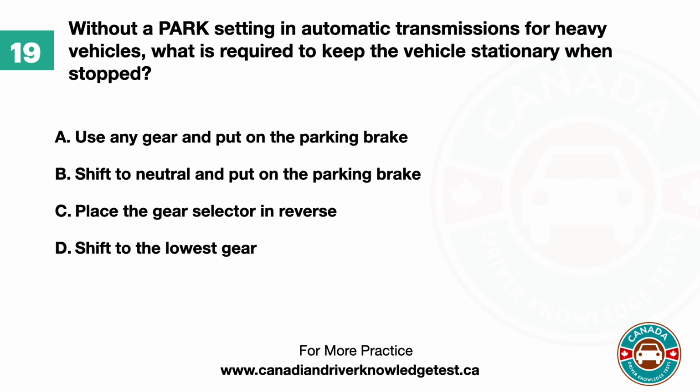Question 19. Without a park setting and automatic transmissions for heavy vehicles, what is required to keep the vehicle stationary when stopped? A. Use any gear and put on the parking brake. B. Shift to neutral and put on the parking brake. C. Place the gear selector in reverse. D. Shift to the lowest gear. The answer is B. Shift to neutral and put on the parking brake.